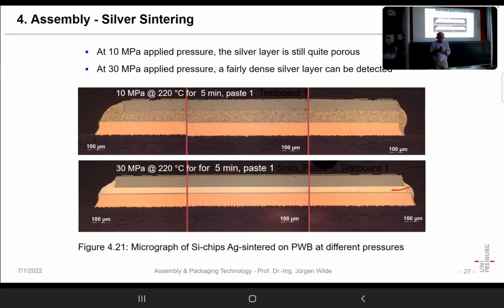So here we were in a trap, you could say. And that trap was eliminated by using a different die attach material. I think the basic ideas of that die attach go back to the Siemens company and the University of Brunswick in Germany. There was a famous PhD work on that, and they invented silver sintering.